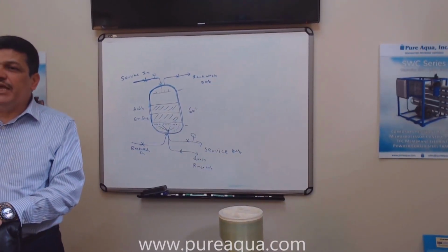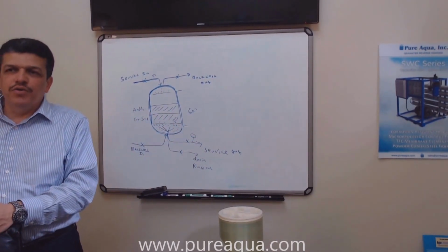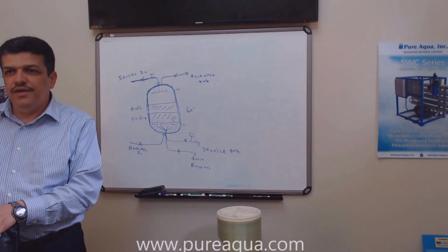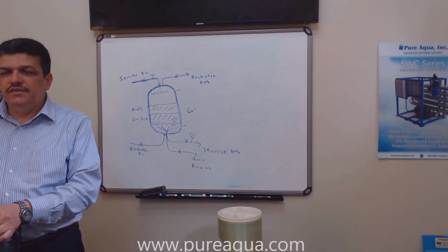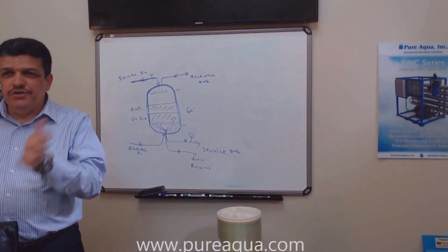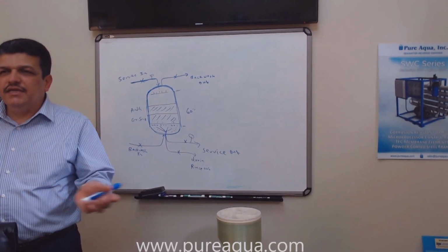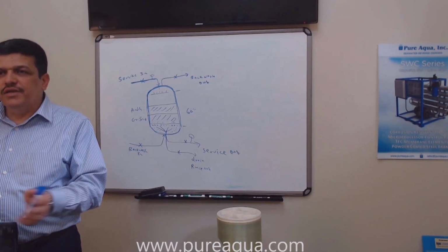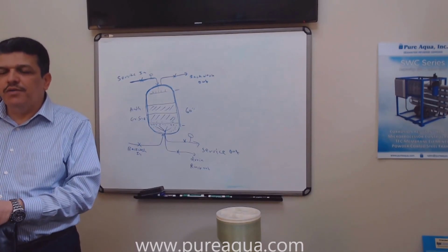Now, for seawater applications, if what you're filtering here is seawater, I would definitely go with fiberglass. If we are filtering water that has high chlorine, I would never go with stainless steel, honestly, because we know that chloride is the first enemy of stainless steel. You're going to start having a lot of problems with it. It also depends on the industry. The beverage industry always likes stainless steel. In cases like this, we would do some special lining for them, like glass lining or some special coating inside, because they do something called steam sterilization with the carbon filtration.